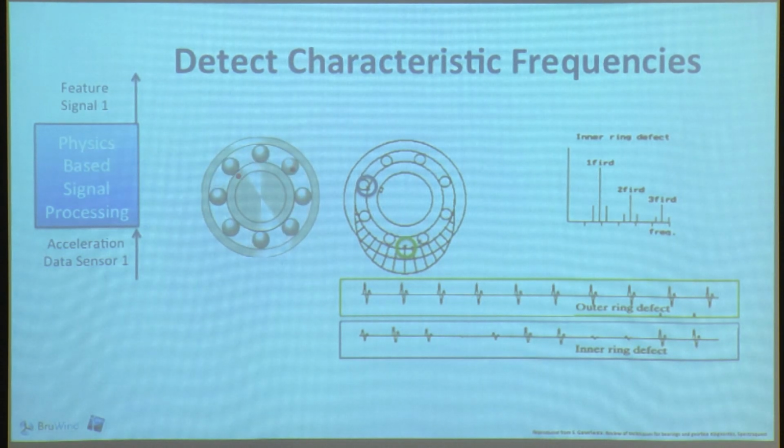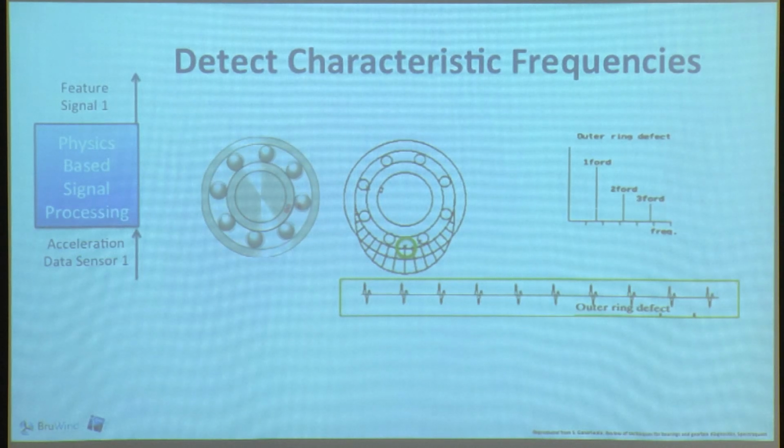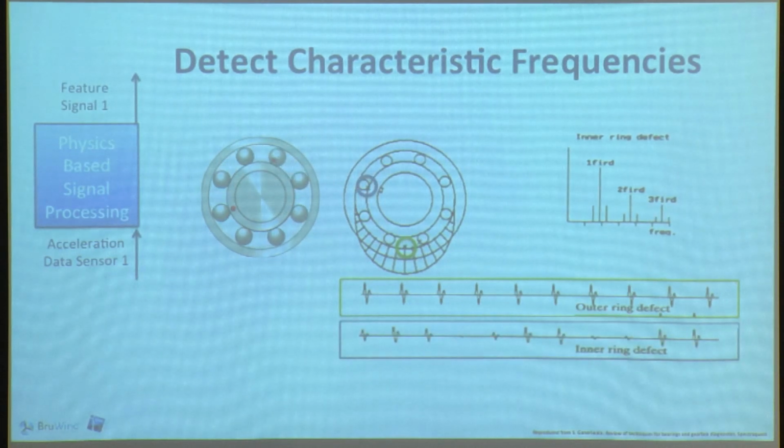So this again gives you a very distinct frequency signature. You have a frequency and you have sidebands. The sidebands are related to this going up and down of the force. Again, you can extract this. If you look at the spectrum of the acceleration, you can say, okay, I see this peak, it's linked to this bearing inner ring, so there's a problem there. So it gives you very detailed information about where you have an issue, and you get a very distinct signature for it.